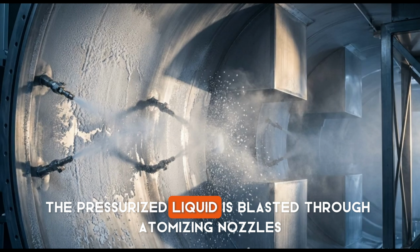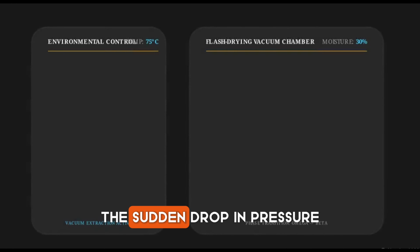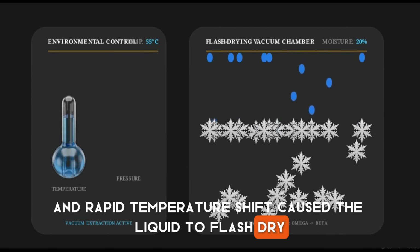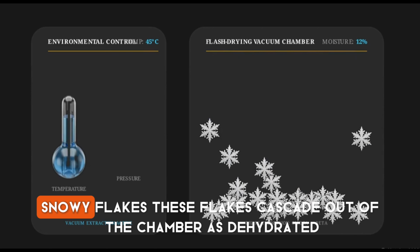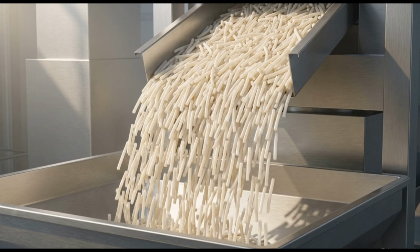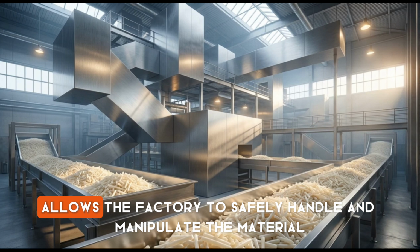The pressurized liquid is blasted through atomizing nozzles into a vacuum chamber, hitting freezing steel walls. The sudden drop in pressure and rapid temperature shift cause the liquid to flash dry, crystallizing into delicate snowy flakes. These flakes cascade out of the chamber as dehydrated, standardized base soap noodles. Converting a boiling fluid into a predictable dry particulate allows the factory to safely handle and manipulate the material at